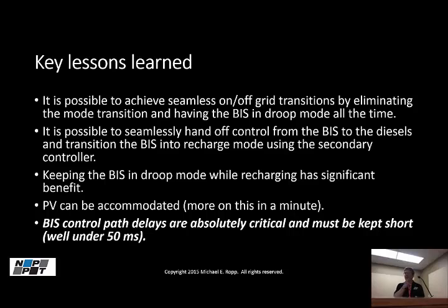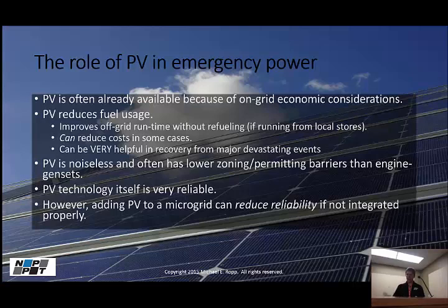So I mentioned, a lot of people want to add solar to their microgrids for extra resiliency. What does the solar do for you? You see the second bullet here? It reduces your fuel usage. There's, I won't call it a standard because I don't believe it's in any way mandatory, but in the Northeast, there are some requirements being suggested for how microgrids should be configured to make them most beneficial for situations like this. One of the things they're encouraging is at least 14 days of off-grid autonomy in your microgrid. And if you think about it, that is a long time.